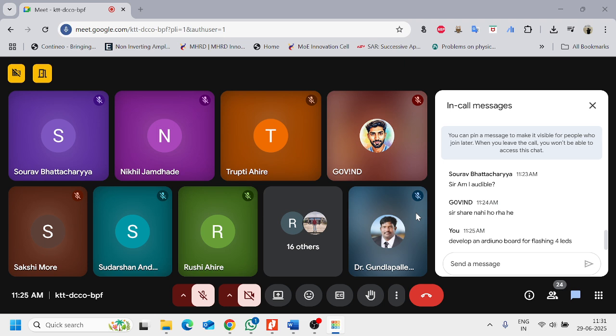So when I actually run this and I press the button, it will just blink it. But when I don't press, it will stop because there is no other action. All the actions are inside the if. In case the button status is low, which means if anybody presses the button, then it will run these selected codes.